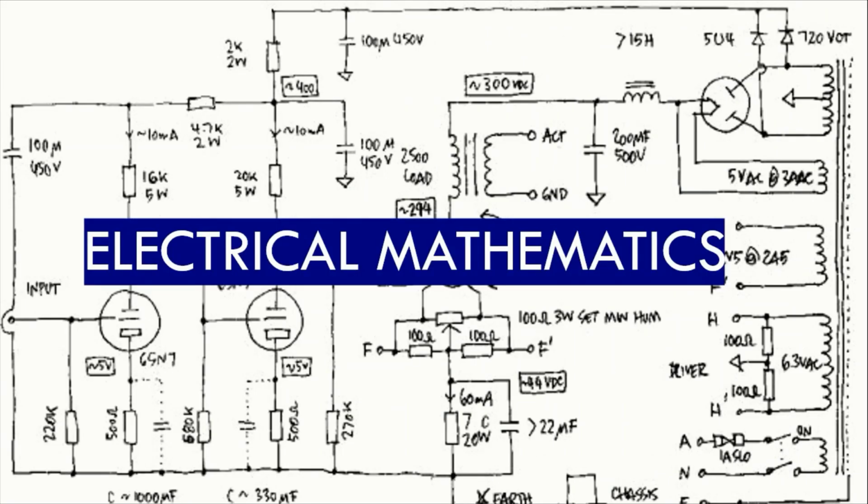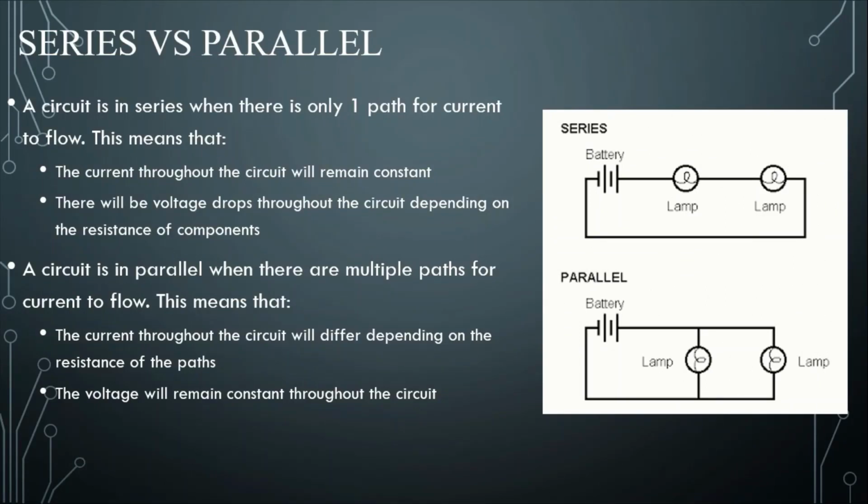Now we'll go into electrical mathematics. So first thing you need to know about electrical systems is the difference between a circuit in series and a circuit in parallel. A circuit in series has only one path, as you can see in this. It goes around and back. It only has one way for current to flow. And since it does, it'll have a constant current throughout it, but there will be voltage drops depending on the resistance of components. In this case, since they are the same, they would have the same voltage drops.